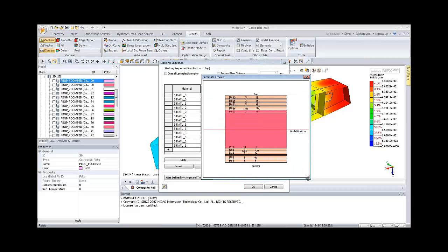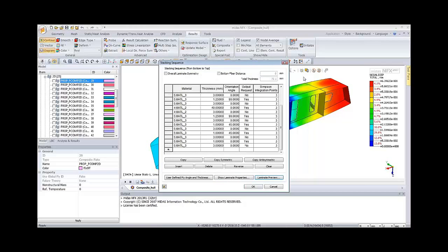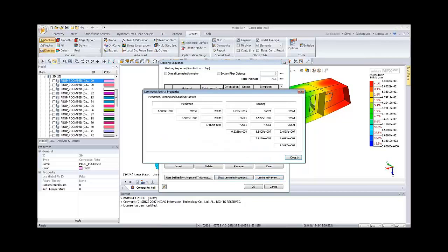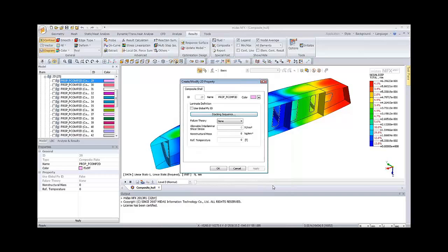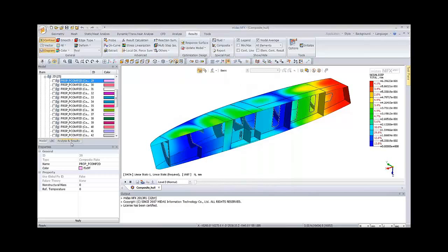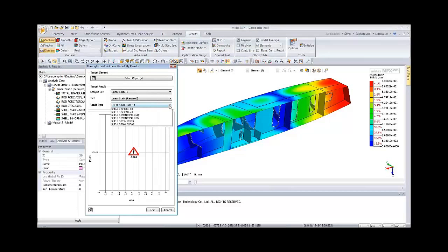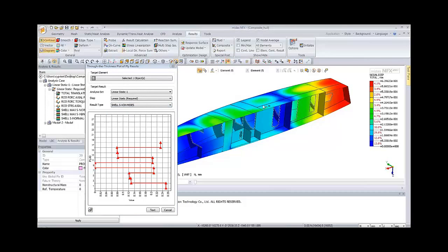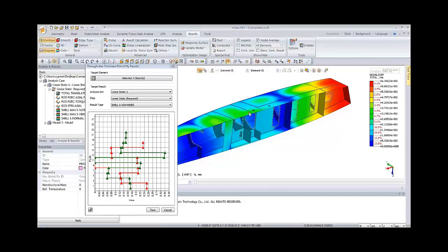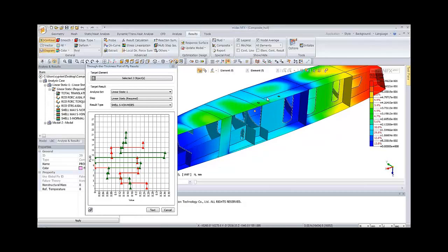And you can also use the tool I've shown, the through-the-thickness plot, in order to see the results ply by ply. So for 4 meters stress, for example. So you can check several positions of the boat to see the difference between the plies in this window.